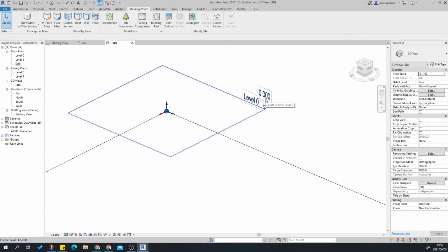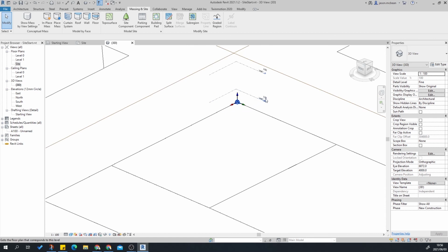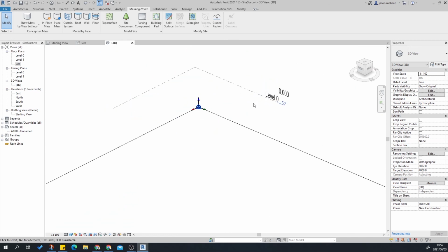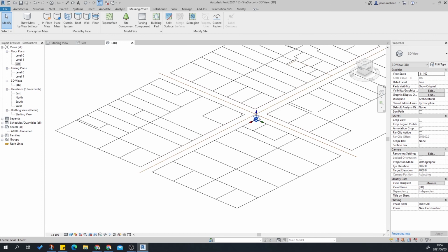So we'll share those levels as well, just so that we make sure that we're all using the correct levels to work from. It eliminates errors. However, when we produce our floor plans, we also use datum. So we'll pick a level to be 0, and then we'll use reference levels in relation to that, so plus or minus if you're going to a basement. But I'll demonstrate how that all works now.